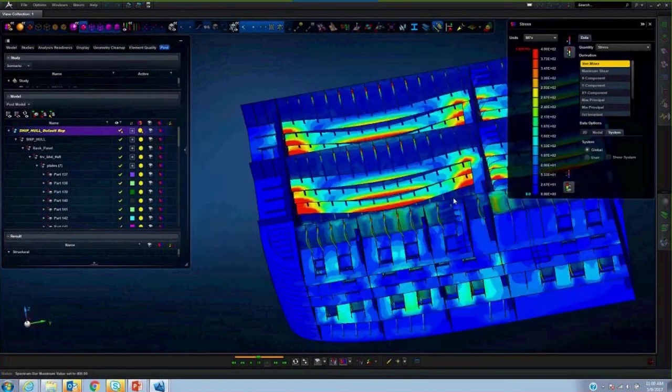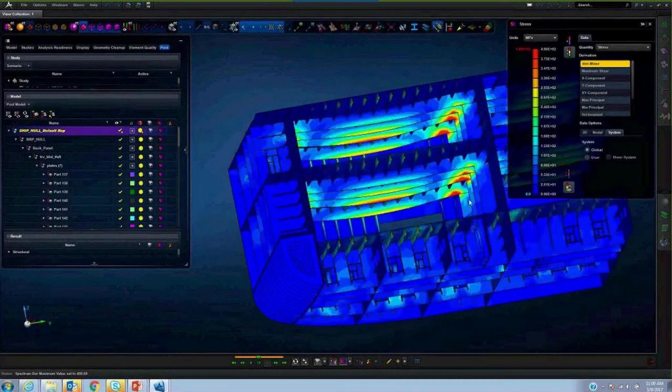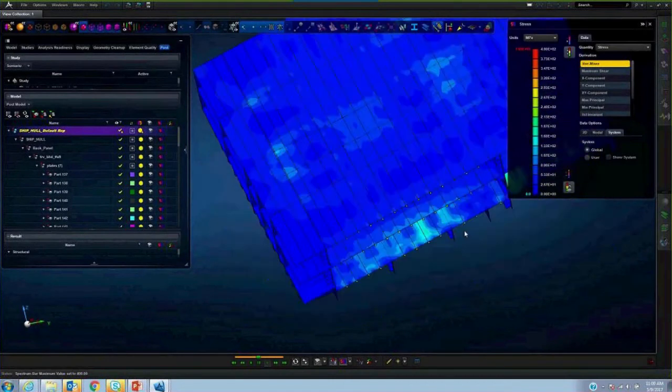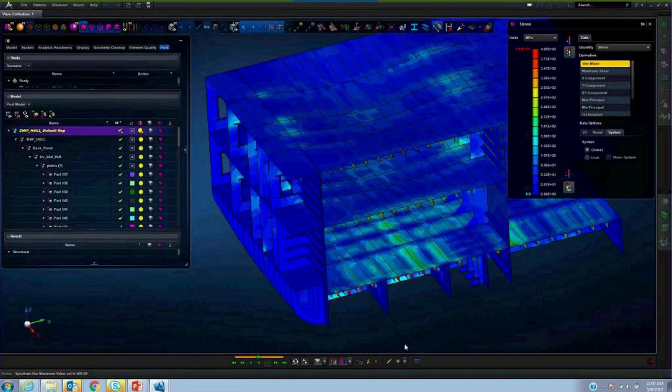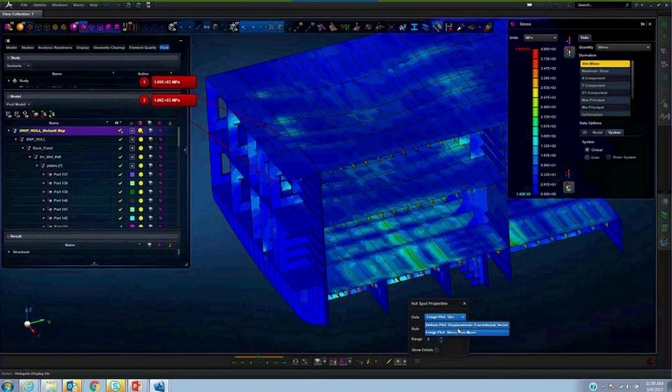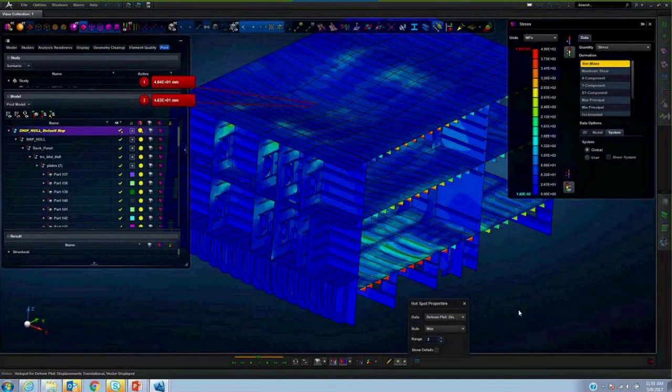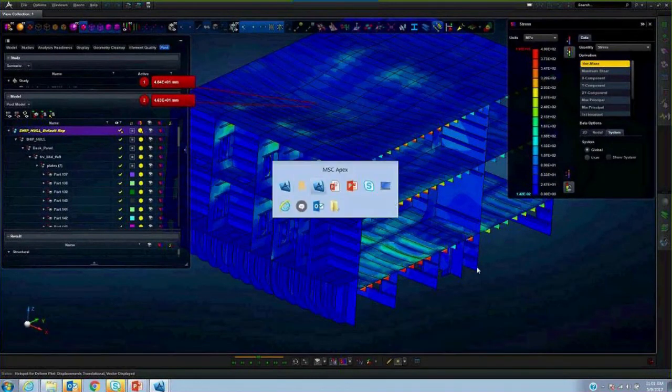And if you see here, now the colors are more uniform here. And more importantly, can we look at the hotspot to see what the numbers are? And can I look at the maximum deflection under this modified design? Okay, now it is 46 millimeter as it's supposed to be 63 millimeter, whatever. There is a considerable improvement, even just making one frame adding to this. So what have we learned?